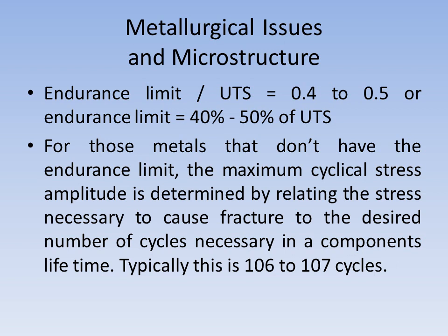That is, what is the stress required to break the item in 10^6 or 10^7 cycles, that is determined. That means cycle is fixed in the x-axis of the SN curve, and the point where the vertical line touches the graph of that metal is noted. The stress corresponding to that point is the limiting stress for that alloy.